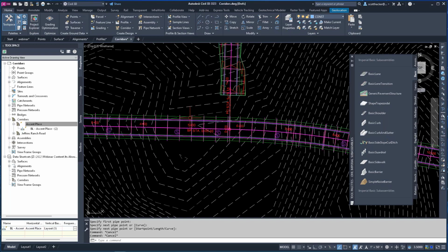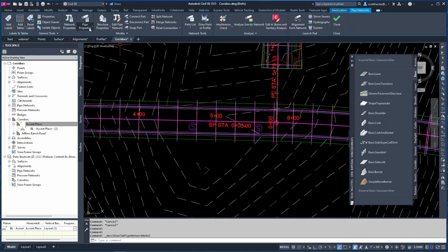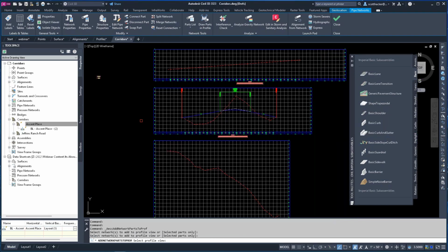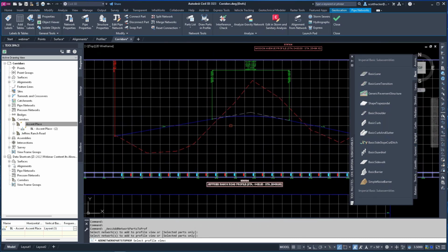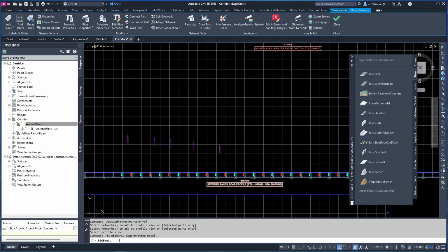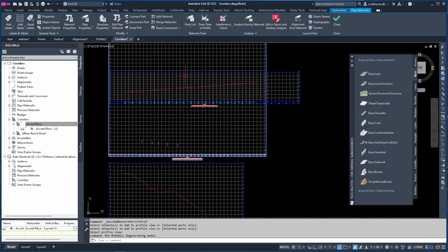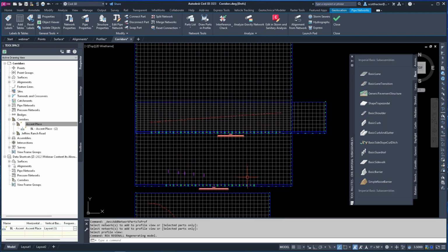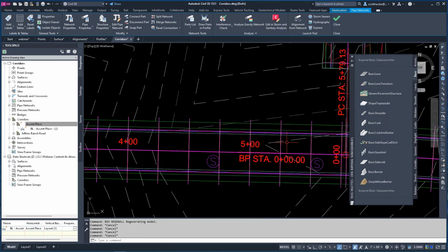All right. So with that, modify pipe network. We'll tie it all together with this. We're going to draw the pipes in profile view, or at least our manholes. Jeffrey's Ranch is over here. There it is. Select the view. I'm going to go ahead and pop that in right there. There's my manholes. Okay. They are not set to a surface, so we're going to get some really ugly situations here. So let's tie them to a surface.